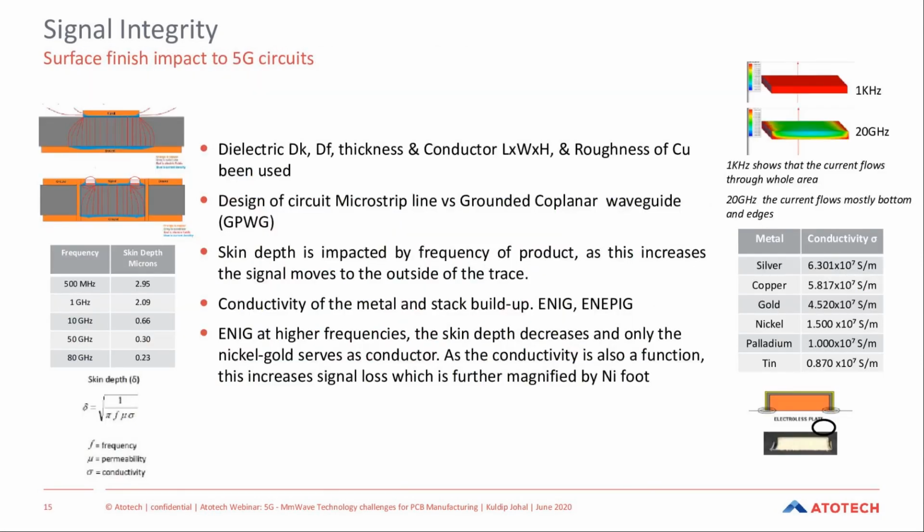In this slide, this is really talking about the impact of signal integrity and the relationship to surface finishes. I've got a lot going on in this slide, and I'm going to start off with one of the key factors that we know: length, width, and height is affected, roughness is affected, dielectric is affected. But another thing that we should pay close attention to is the type of circuit that is being used.